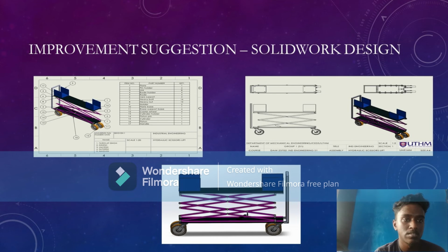After the object is placed on the platform or holder of the scissor lift, the power source will be started. Once it has started, the cylinder will be filled with the hydraulic oil. The cylinder will extend outwards because the hydraulic oil pushes the cylinder to move. The platform will start to rise and move to the destination where the object has to be placed.